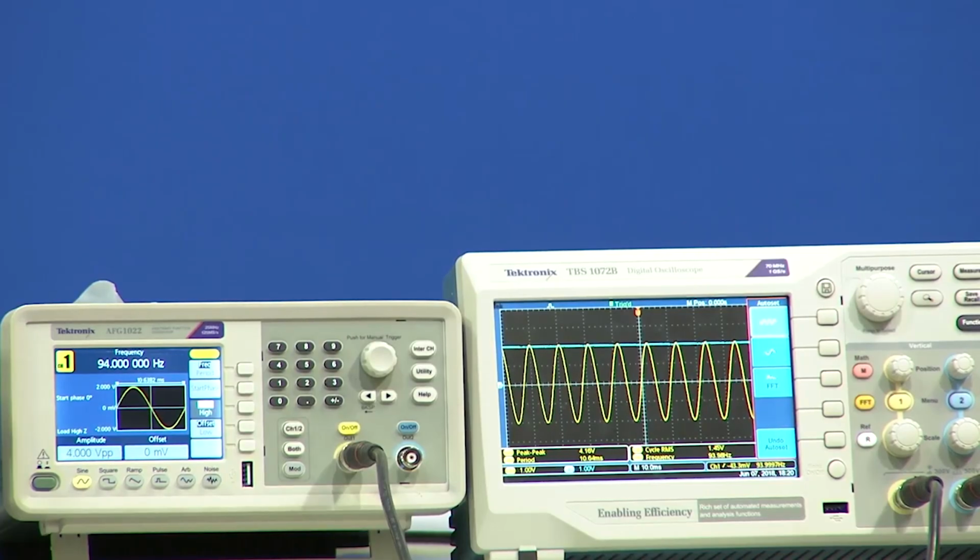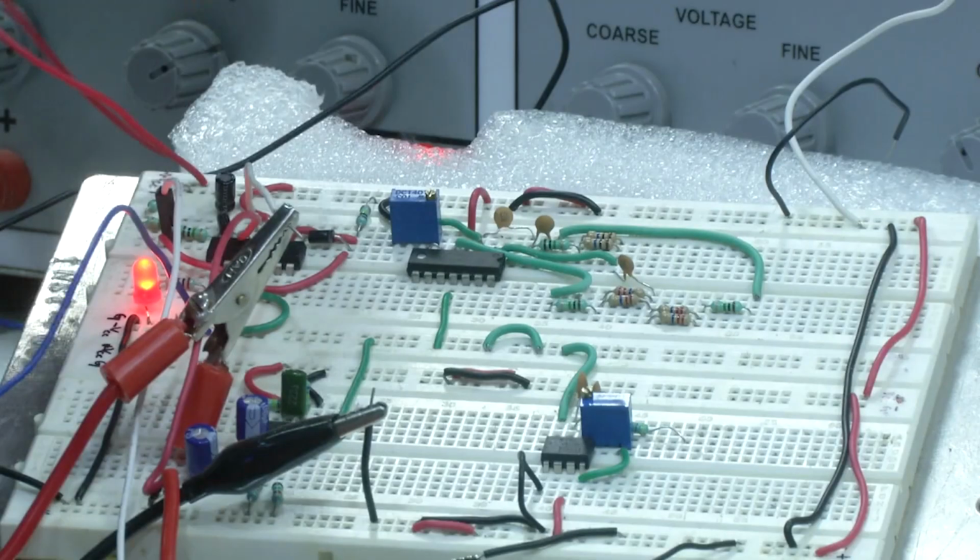Then the next part is, once the peak detection is done, we have to create a threshold. Now if we recall our circuit, we are creating the threshold by using 2 resistances, that is of 1 mega and 2 mega resistor. Why we are using such a high resistance value? Again the reason is not to have any loading effect in the system. So what I will do is connect this particular output terminal, the blue connection, to the resistor junction.